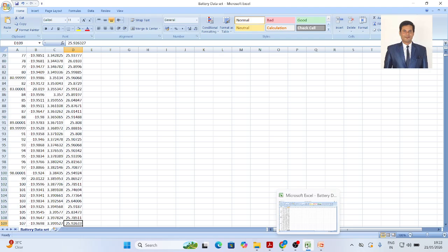OK, what percentage of the Coulomb of charges is remaining relative to the actual values? For example, if it is 60/100 into 100, what is the percentage of state of charge? It is 60%. So that is a formula we are just maintaining for the state of charge, isn't it? I will teach you all the formulas correctly in state of charge and state of health.